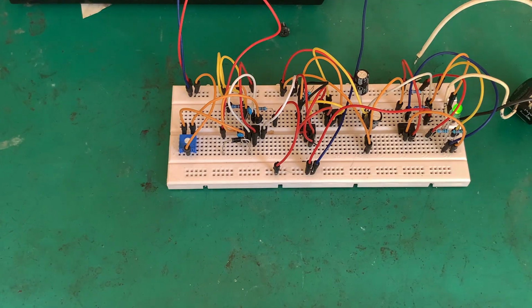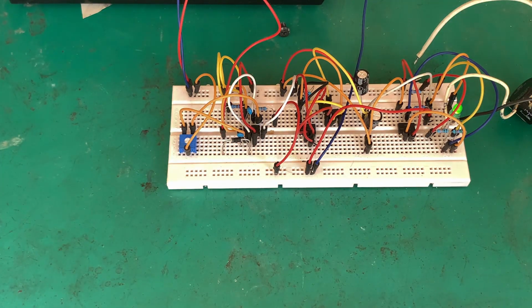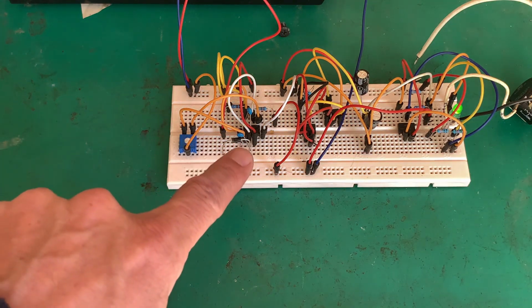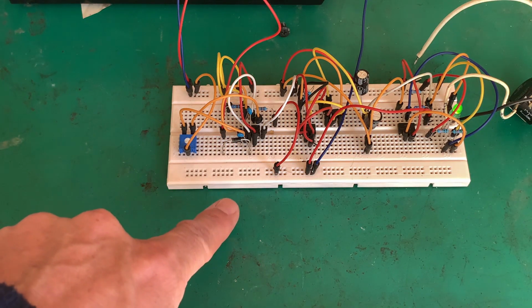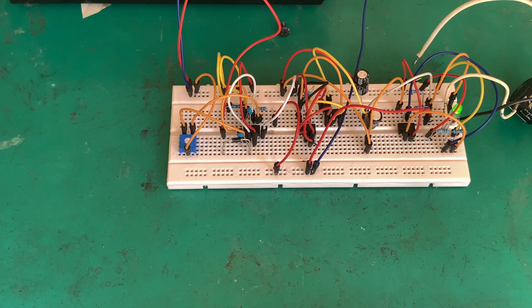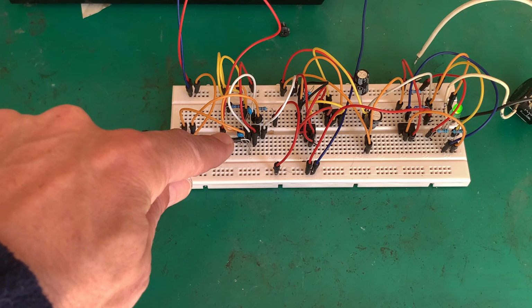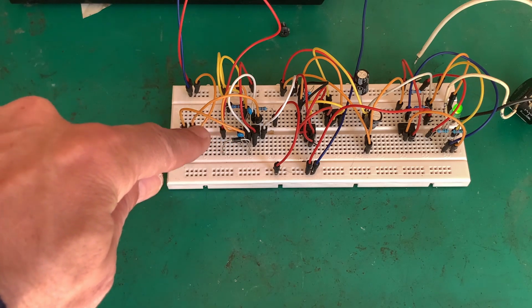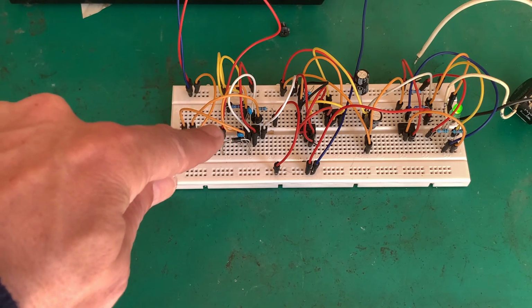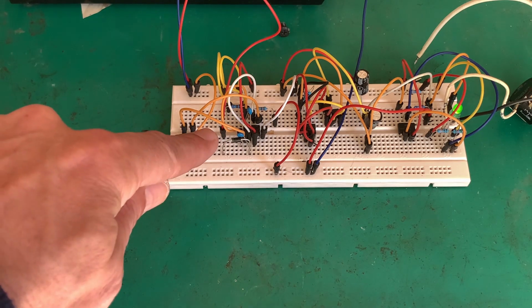Now, why did we create the split rail? Remember, we said we couldn't go rail to rail, but our battery voltage can go to 0, so 0 to 56. Well, I haven't got a split rail on this one, so what you'll see is this will go down to the rail voltage, so we can't go to 0 battery voltage and it will give us a reading. We can only go down to the rail plus offset, so we can go down to about 2 volts on this circuit because of the loading.